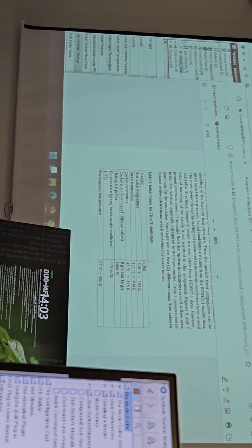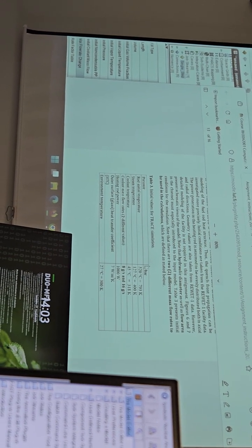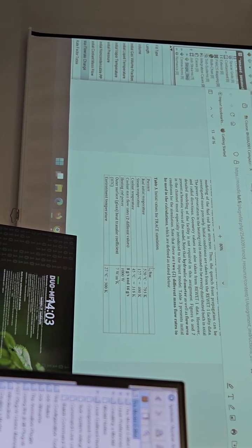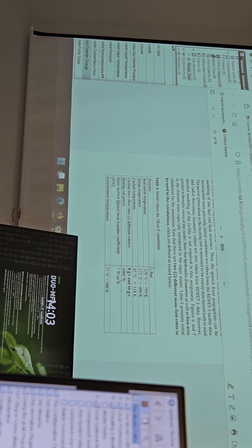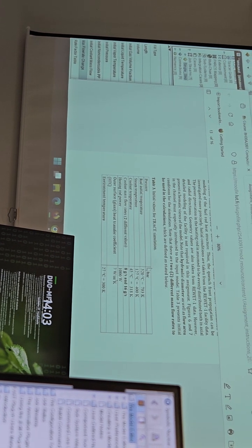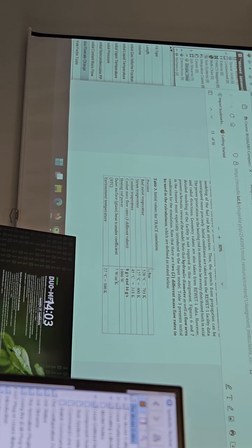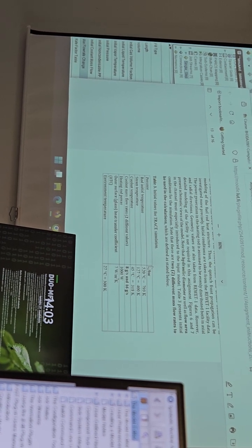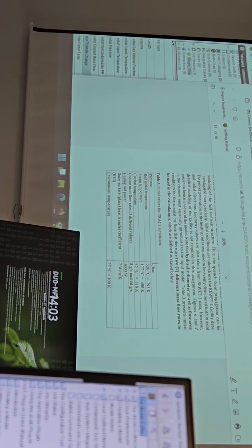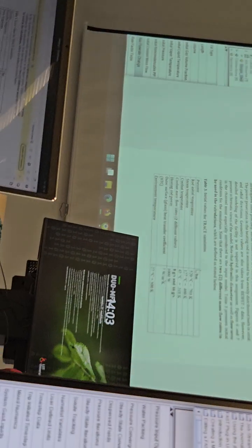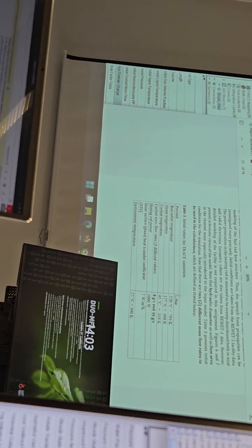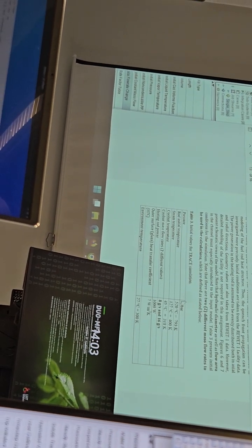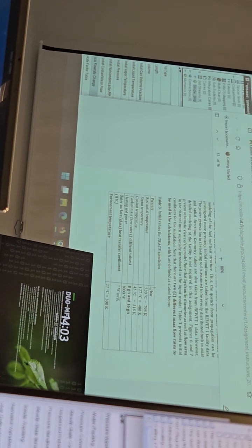It will mostly affect the fuel rod temperature and the speed of quench front propagation. The higher the flow rate, the faster it will flood the system, the faster the quench front propagation. Also, since the mass flow rate is higher and the cross section is the same, the speed of the coolant is also higher. Reynolds number higher, Nusselt number higher, so then the heat transfer is more intensive. You can also write this in the report when you have to explain why.